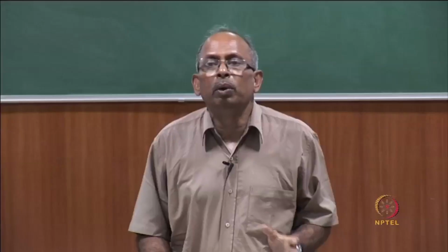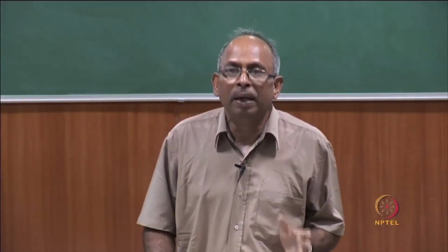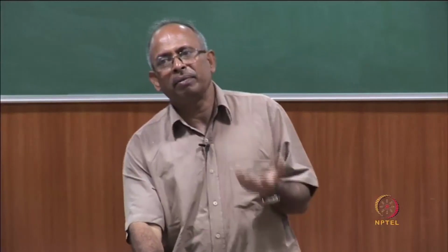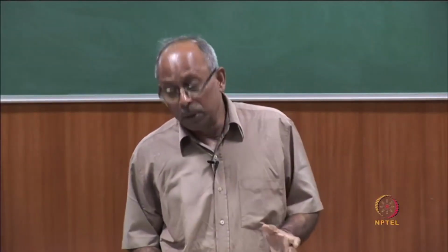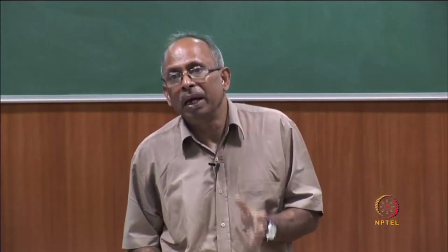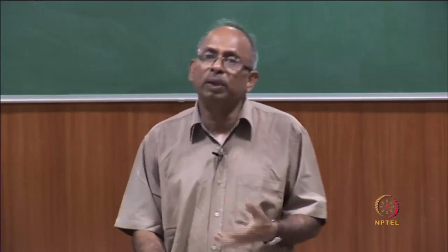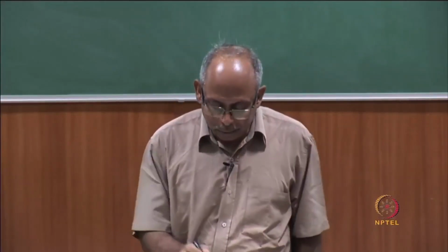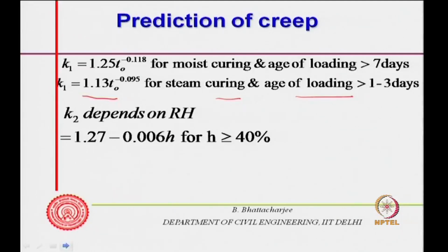See, age of loading would be most of the time more than 7 days. It rarely would be less than 7 days, right, because of deshuttering etc. After that, even construction load, most of them will come. But if you are doing steam curing, then load can come fairly early, because steam curing is done to attain high early strength. So, that load can be applied easily. So, this is again a kind of empirical guideline available.